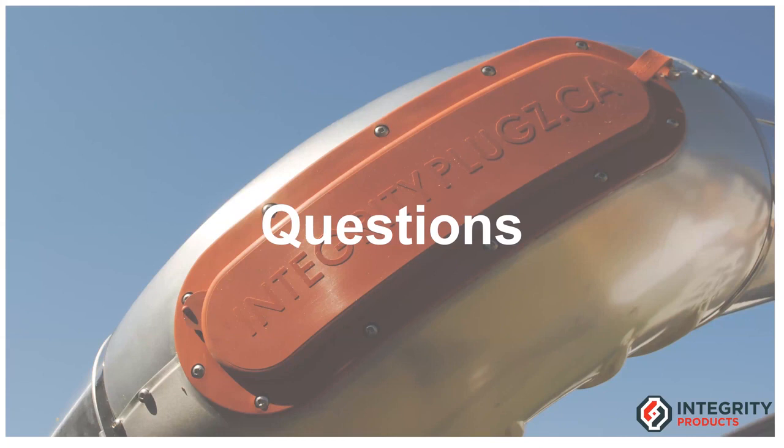I see one of our first questions here, Matt, is asking what the temperature ranges of the silicone and EPDM inspection ports are again. Our silicone inspection ports work from -150 to +450 Fahrenheit, and that 450 Fahrenheit is a constant contact temperature. It's about 232 degrees Celsius, I think it is. And then our EPDM variant is -58 Fahrenheit to +300 Fahrenheit, so 150 degrees Celsius.